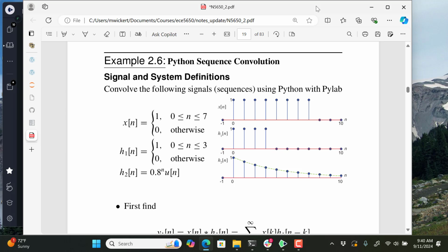You can find out about a function called filtfilt, which scipy.signal has and MATLAB has. So filtfilt is filtering twice. You filter the signal once in the forward direction, bring it through, and then after it's been filtered, you take that array, flip it over, and filter it a second time, time reversed. What do you think that does?